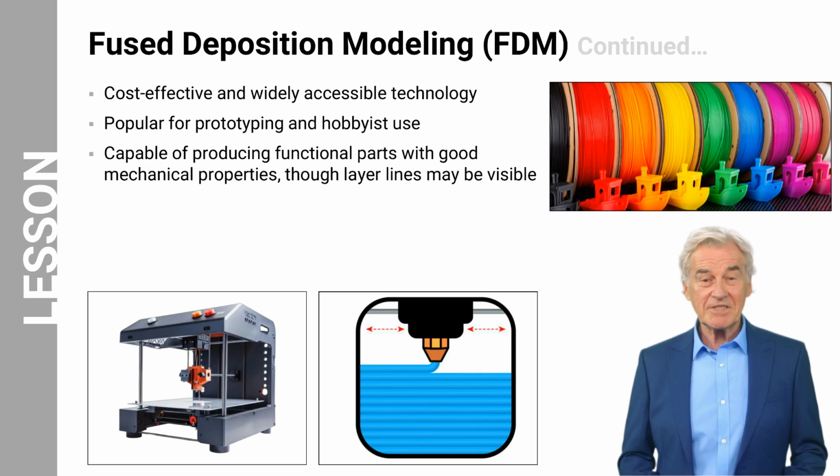What makes FDM particularly attractive is its cost-effectiveness and widespread availability, making it a go-to choice for both prototyping and hobbyist projects. While the final parts boast good mechanical properties suitable for functional use, you might notice visible layer lines in the finished product, though this rarely impacts performance.